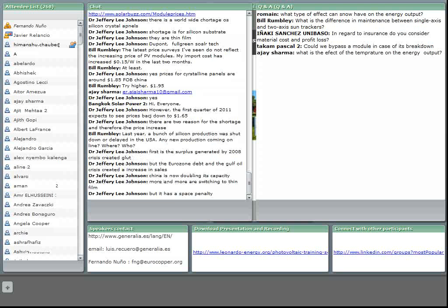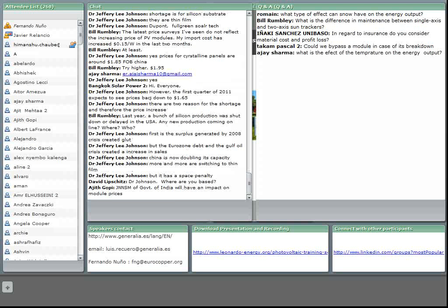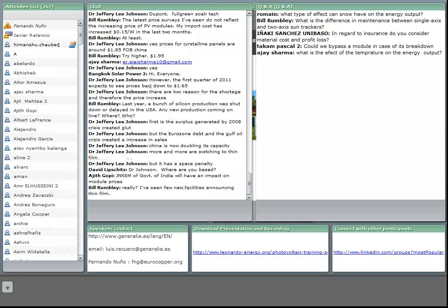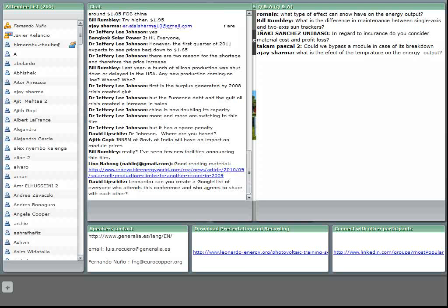There are other elements that might be affected by the temperature, but the main elements are the modules. Then we have to consider that the inverters have to have a certain temperature range, and if we exceed this temperature range, we will have to install a cooling system. But well, that depends on our facility and is not normally considered in general seminars like this one.